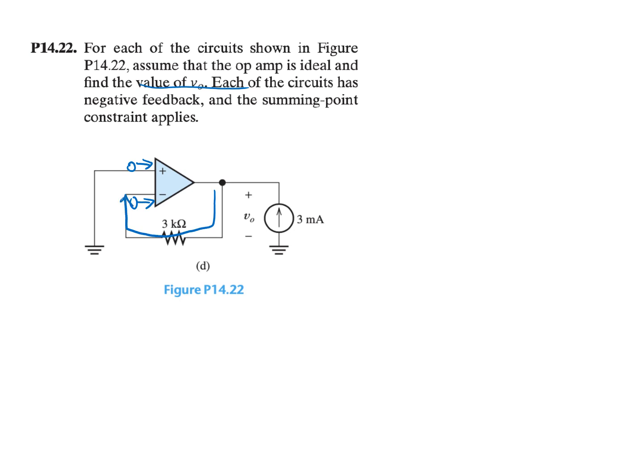So this is actually a dead branch. So now the only current here is the current provided by the 3 milliamp current source, because there's no current through here, so all the current flows like this.